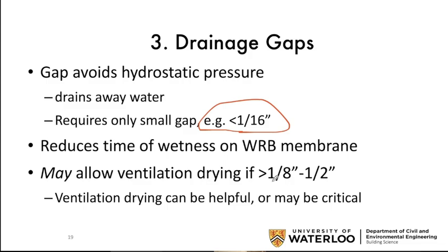Now, if you make the gap larger, and I would argue that in almost all cases, we're talking about more than 10 millimeter gaps. But there are cases where smaller gaps are effective. You can let air flow through those gaps, and that helps on the drying side. Some materials, but it's not always necessary.